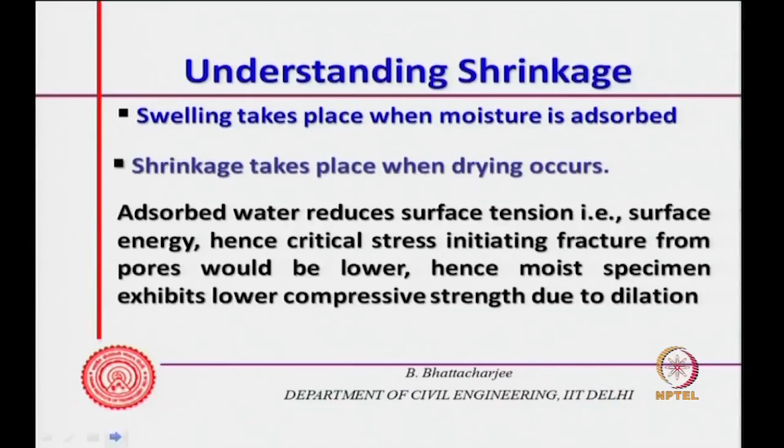Now, surface energy is reducing when the specimen becomes moist, and therefore critical stress reduces. Therefore, a moist specimen exhibits lower compressive strength due to this dilation effect. So, this is going back to our situation.